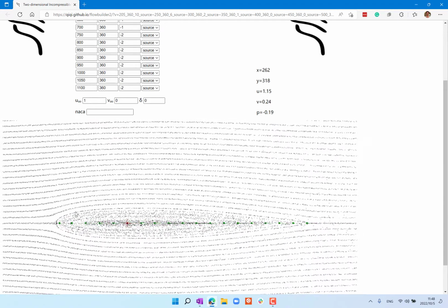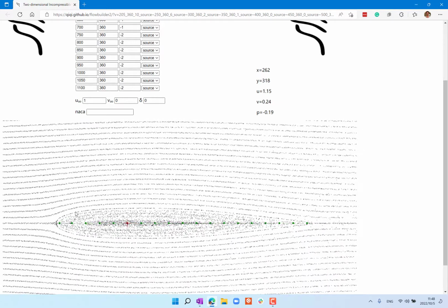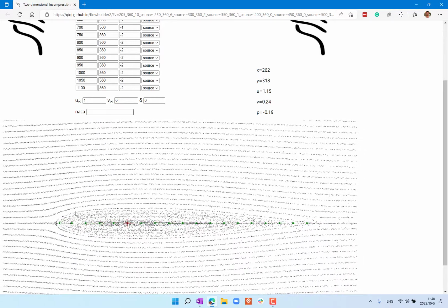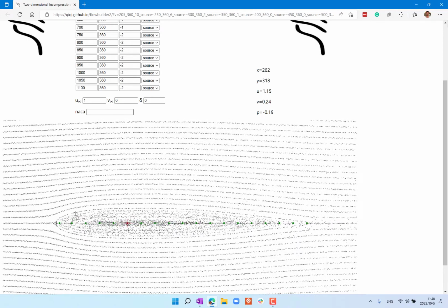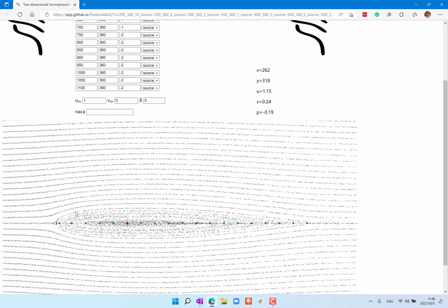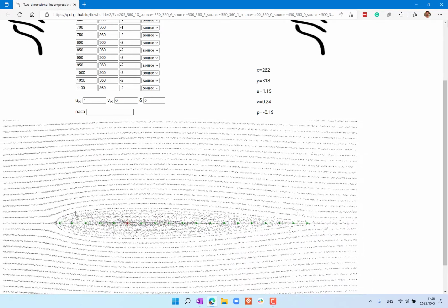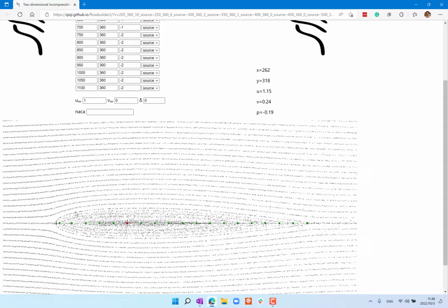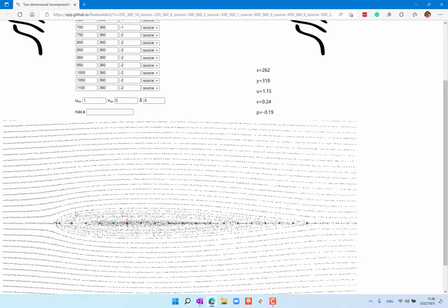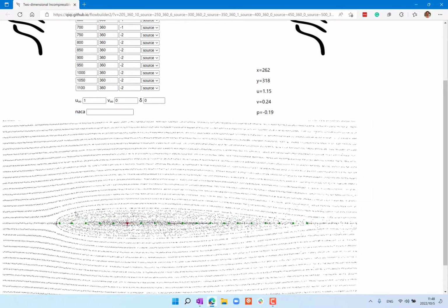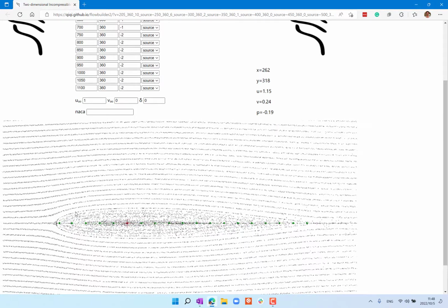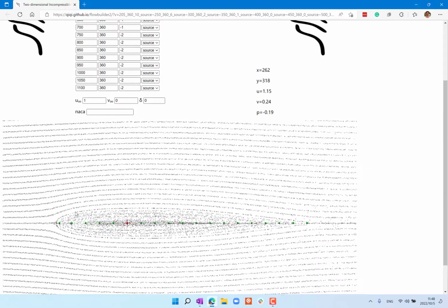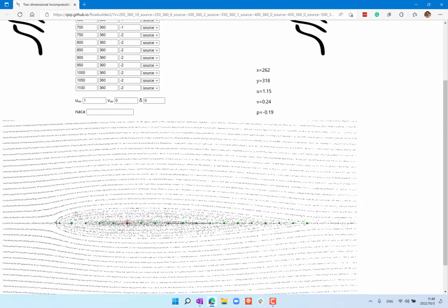Also, the distribution of pressure, as we are going to see a little bit later in viscous flows, is going to determine very much whether the flow is going to separate, and where it will separate. If you are moving along the solid surface and the pressure increases pretty suddenly, that's a location where the flow might separate. That's another reason why we think about pressure distribution.